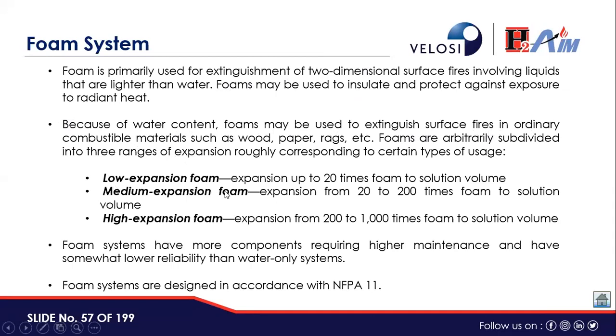So low expansion foam has expansion up to 20 times, medium expansion foam 20 to 200 times, and then high expansion foams are also there, which expand from 200 to 1000 times the foam solution volume. Foam systems have more components requiring higher maintenance and have somewhat lower reliability than water spray systems. And NFPA 11 provides guidelines for foam systems.